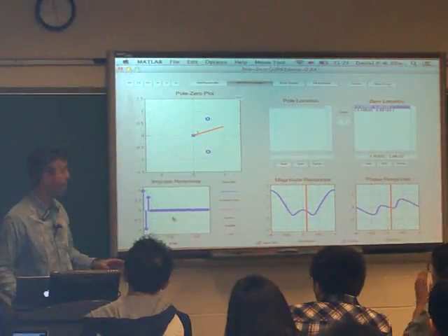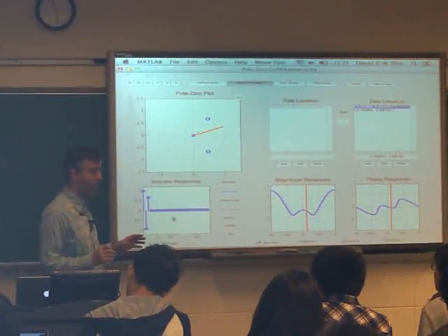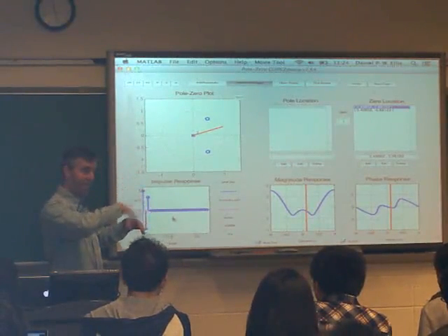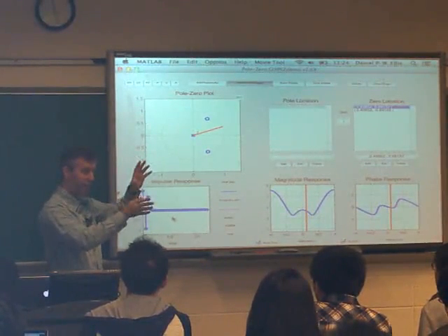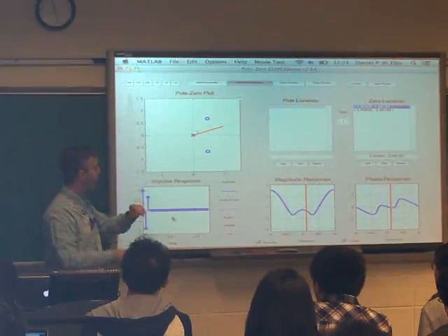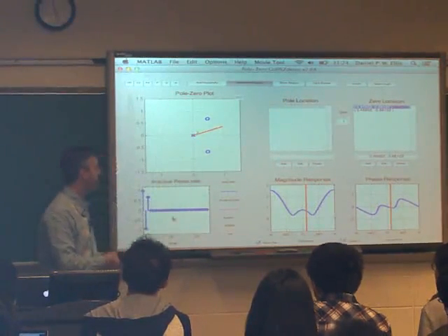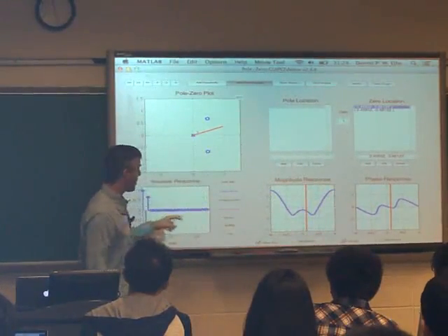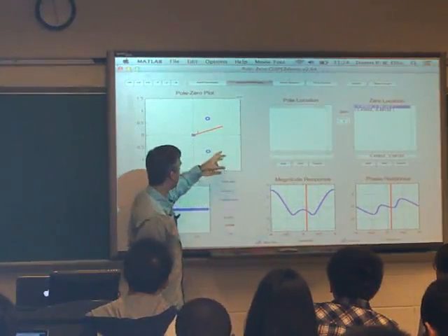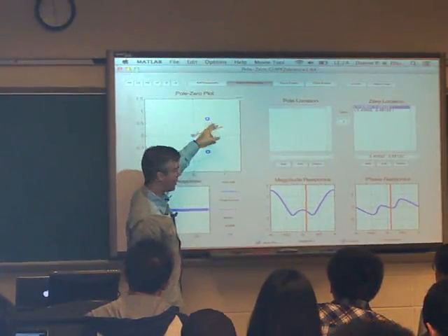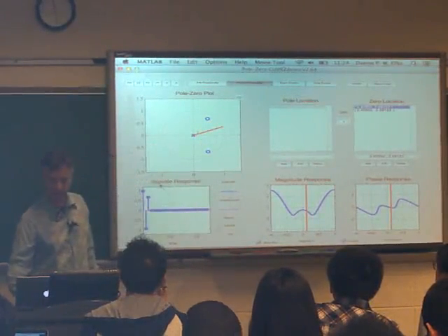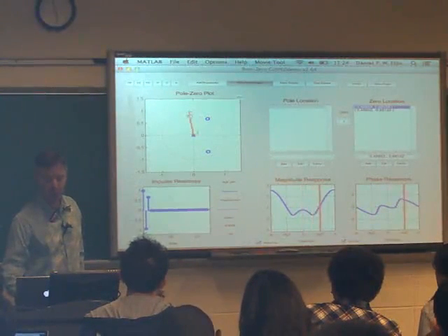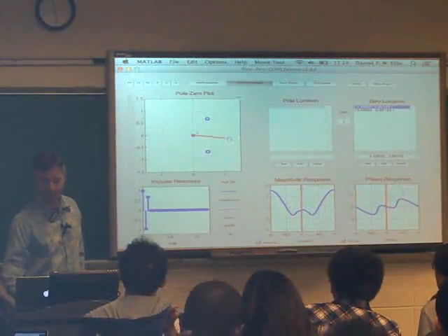So that's interesting. These two zeros here give me this. It's a system with two zeros, which means it actually has to have a finite impulse response with three values, right? It's just three deltas, three alphas, gives me a second order polynomial in z, which has two roots here. Here are the zero locations. Here's the impulse response, and here's the magnitude response, which is what we expect, that it goes down closer to zero as we approach these points here. There's a minimum in the magnitude. Then it floats up elsewhere, right?